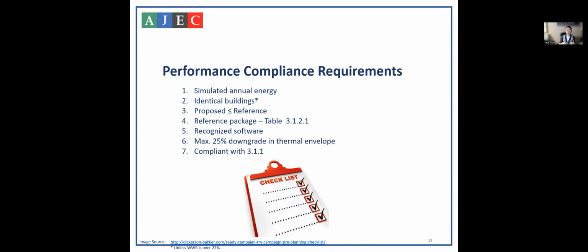So in Toronto, we're at 3,900 heating degree days, and the limit is 4,999 heating degree days belongs to zone 1. Anything 5,000 or higher, it's zone 2. And whatever you're building, you need to pick the reference package for the location where your house is going to be built. That's really critical. So make sure you don't use the wrong table to pick your reference house.